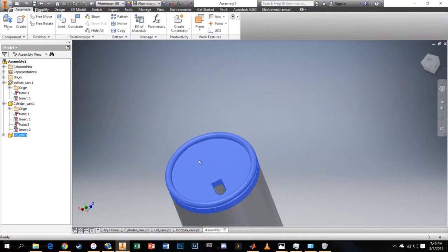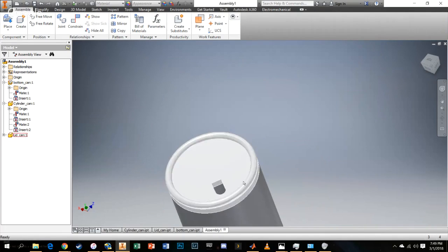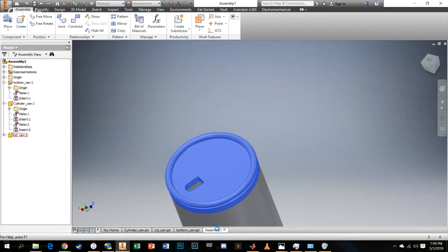So as you can see, we've constrained it so they touch, and we've constrained it so that both the outer perimeters have to be aligned. And you couldn't see this on the bottom, but it can still move. It still has 1 degree of freedom. You can still take this and rotate it, right? Because it's not validating those constraints. They're still touching and they're still aligned with their perimeters.